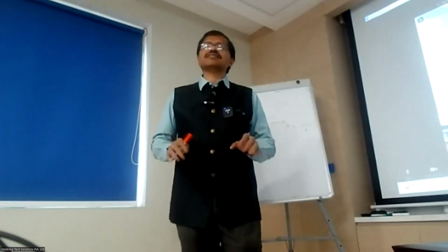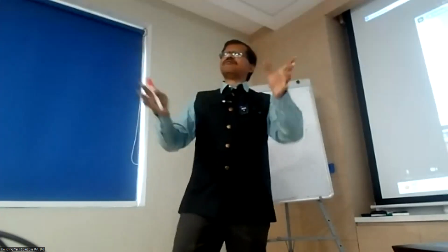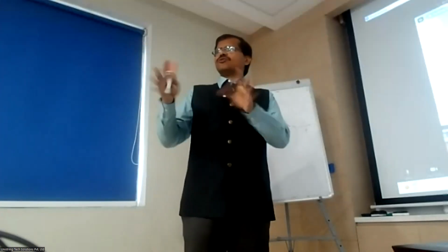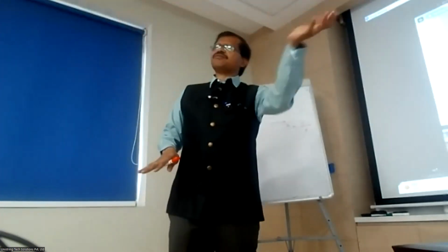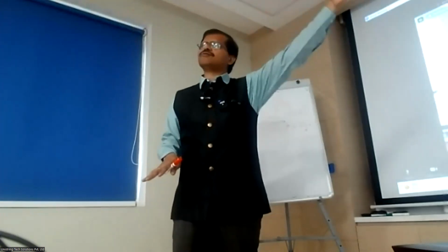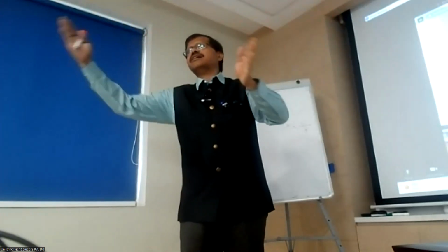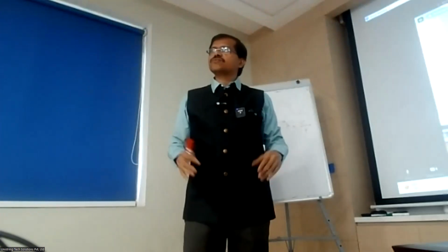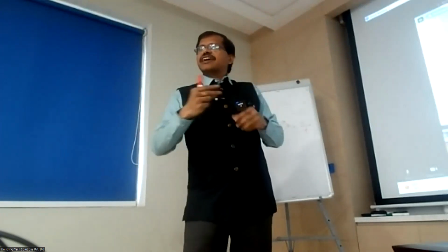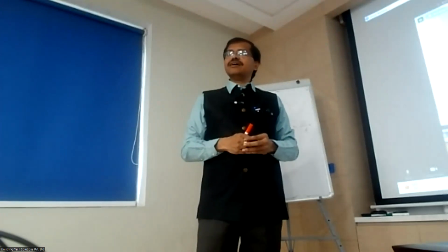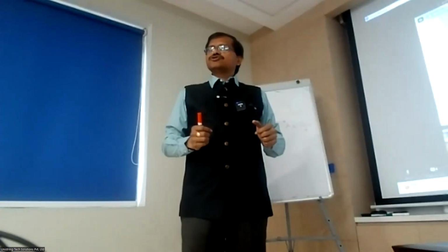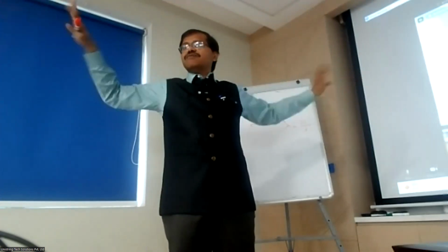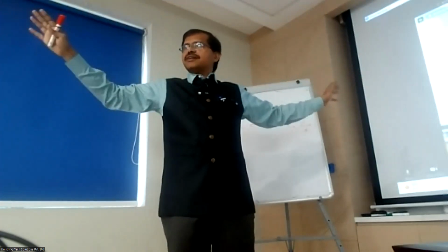What is this trade-off? If I say I'm okay to measure with a 1 meter per second resolution, so if the real velocity is 0.9 meter per second, just give 1. 1.1 also you give 1, that is enough. If it is 1.6, you give 2 meter per second. I am only interested in a 1 meter per second level resolution. Then the radar can give a reading in a millisecond also. Why? You are not demanding very precise information in frequency, right? So if you demand very preciseness in frequency, you need a very long time, inversely proportional. Are you getting my point?